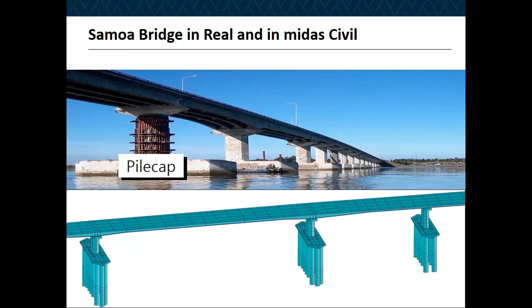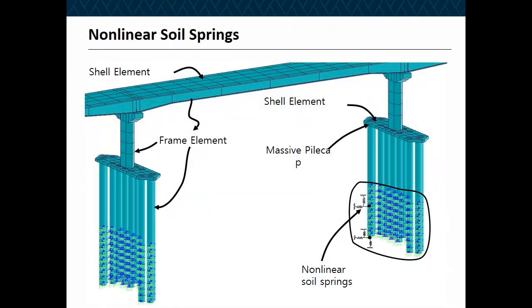So it is very important to make sure you include the pile cap mass and, if you can, the pile foundation as part of your global system. So all the mass participation will come as real as possible.